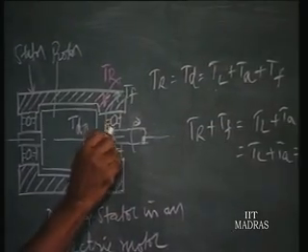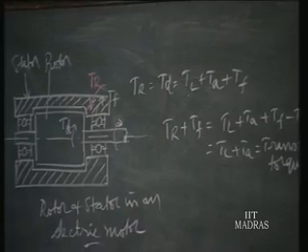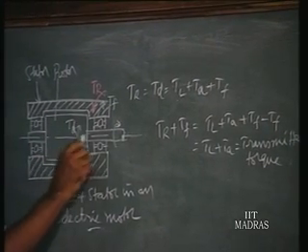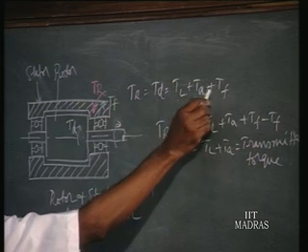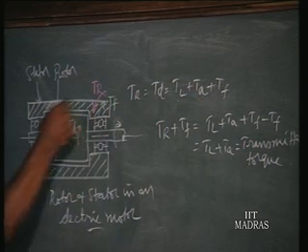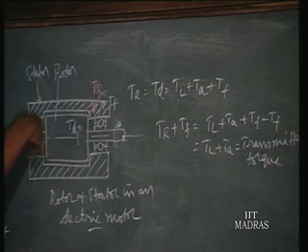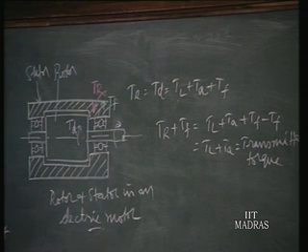This friction is there in overcoming friction between the ball and race. So we find the torque developed TD is equal to TL plus TA plus TF, that is equal to TR. Whatever is developed in the rotor, an equal amount is developed on the stator immediately; that is the reaction.